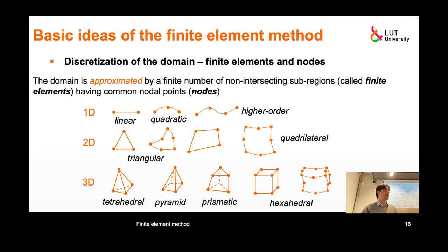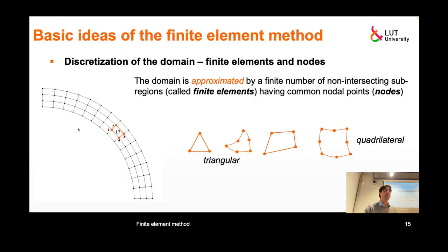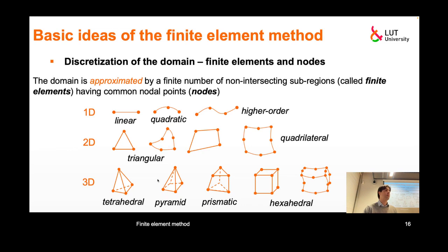Okay, so there is a lot that could be said about how to make this division into subdomains. In engineering practice, it's usually called the meshing process. So this is a finite element mesh, and how to make this mesh for our domain. Usually it's called to mesh the domain, and there are algorithms and strategies, so there are a lot of things, but I just want you to be aware of how it can be in the real world.